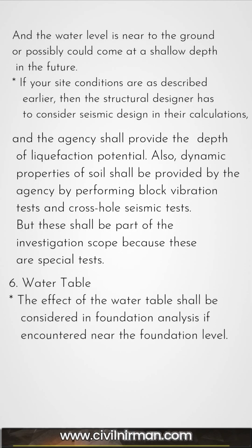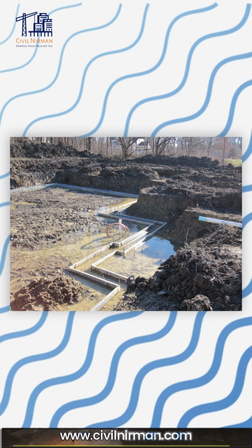The next most important parameter is the water table. The effect of water table shall be considered in the foundation analysis if your site has encountered water levels near the foundation. And the last one is related to your loading intensity and bearing capacity.